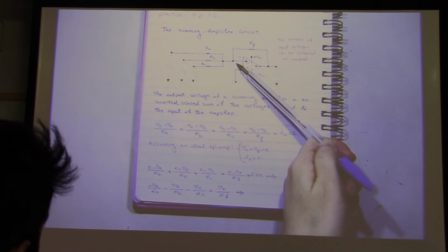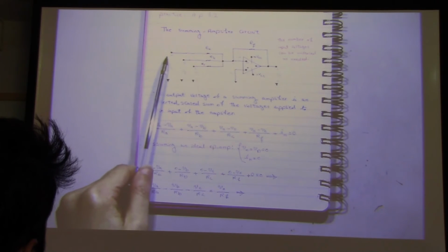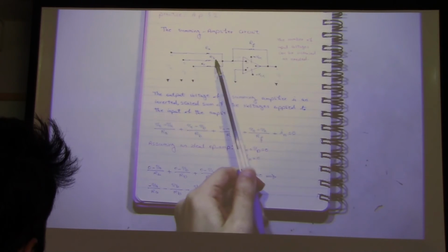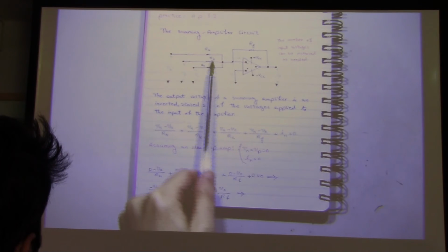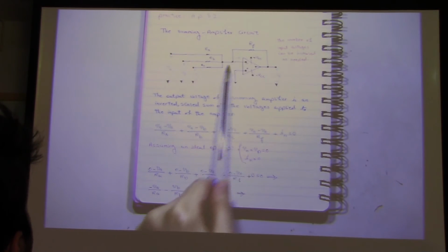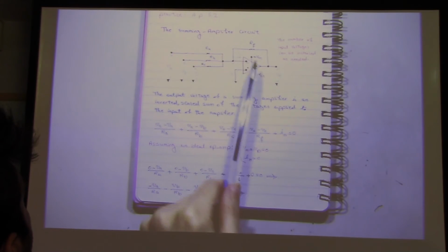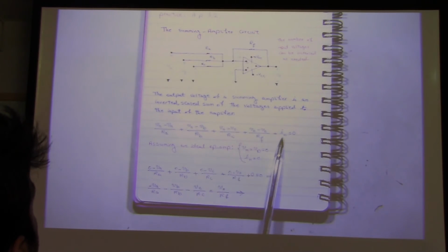Okay, again for this one, write the node voltage for this node. Vn minus Va over Ra, plus the second branch, Vn minus Vb over Rb, and the third one, Vn minus Vc over Rc, plus Vn minus V out over Rf, plus In, it means minus, is equal to 0.